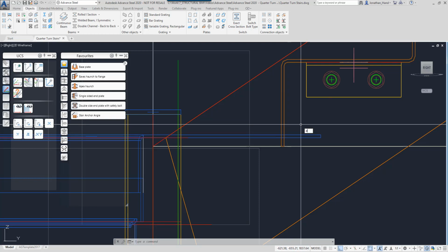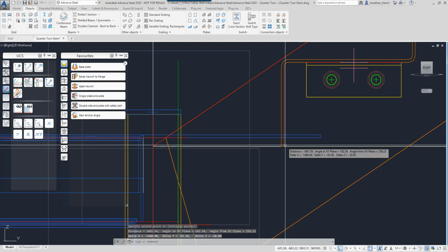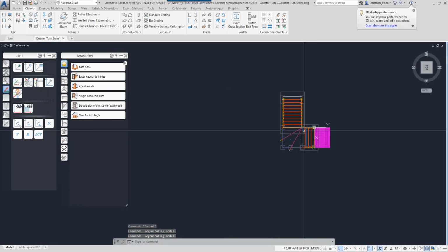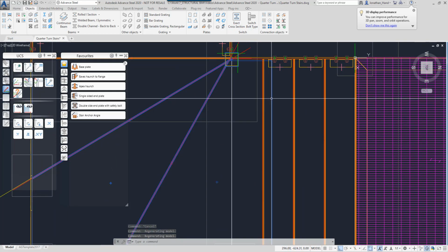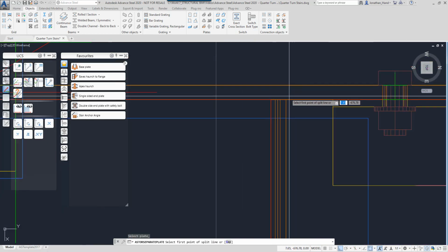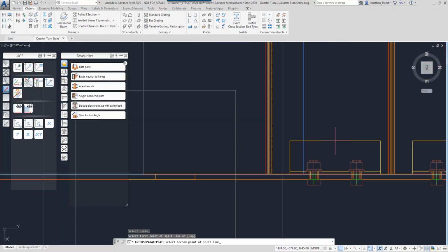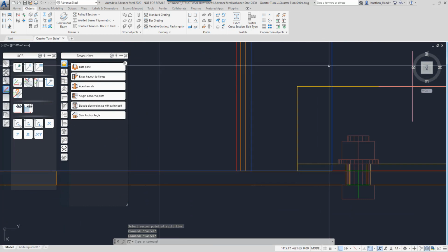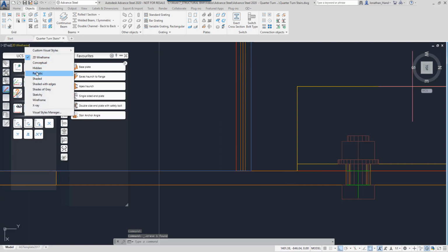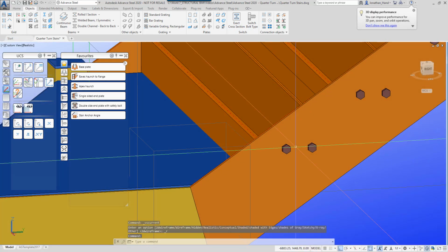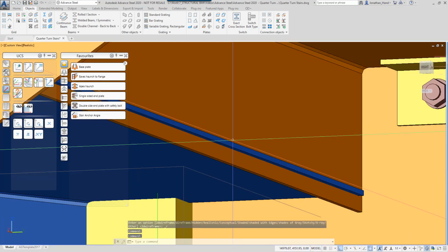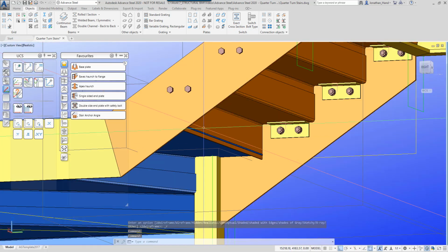So what we will do is just take a quick distance from there to there, and you'll see that it's 60.58. Or what I can do is just split the plate. So if I just split the plate at 2 points, I'm going to say split it at that point from there to there, and you'll see I can then take that little plate out. We just have a quick look, and we orbit that round. So I've split my plate there. I've obviously just split it on the wrong side of the lip, but not to worry.